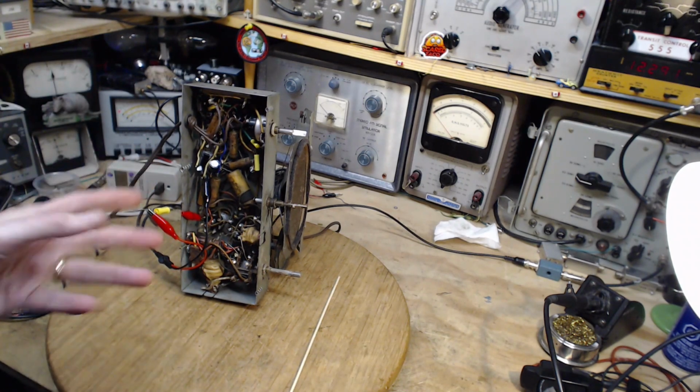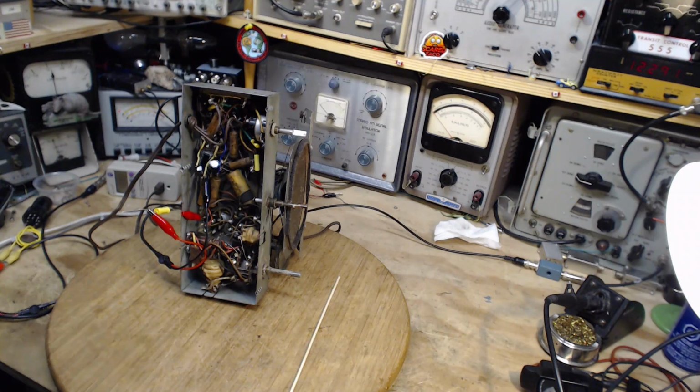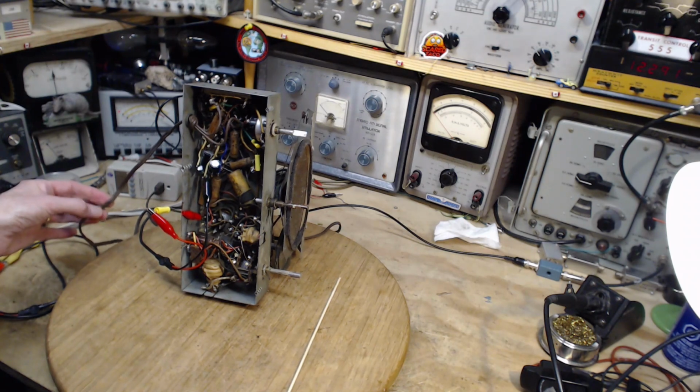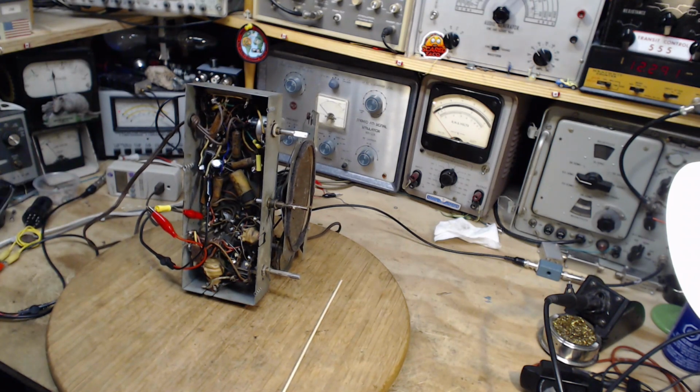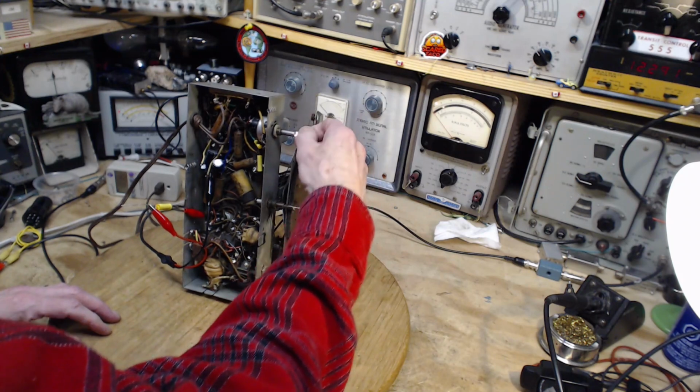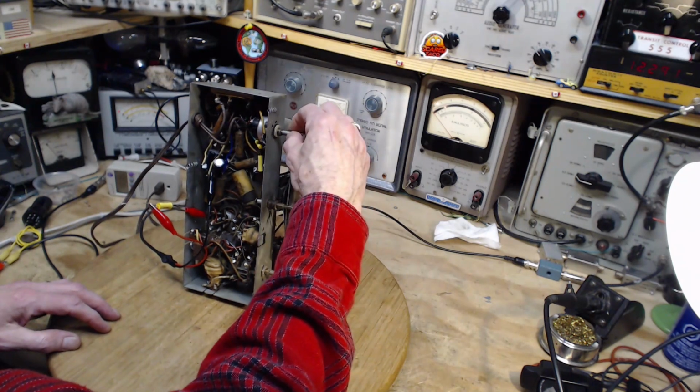Now the reason I can do that, not too much concern, is because I have the radio plugged into an isolation transformer, so it's not plugged into a grounded outlet. So neither of these wires are in any way grounded, tied to the power system neutral or anything like that. It's okay. So now we turn it back up. It is up. Oh, come on.